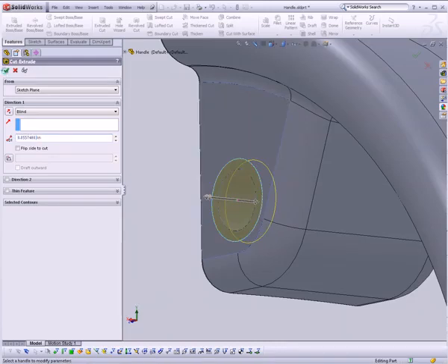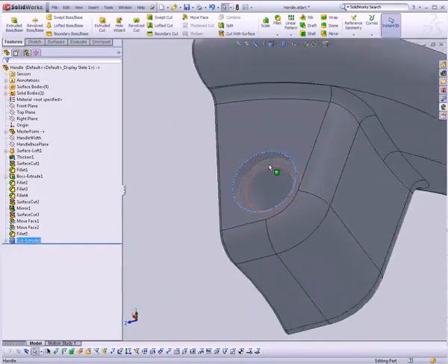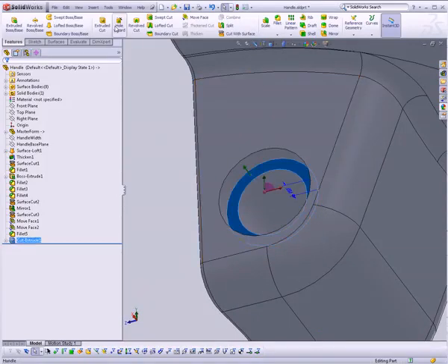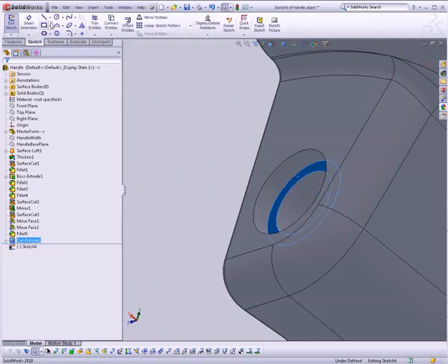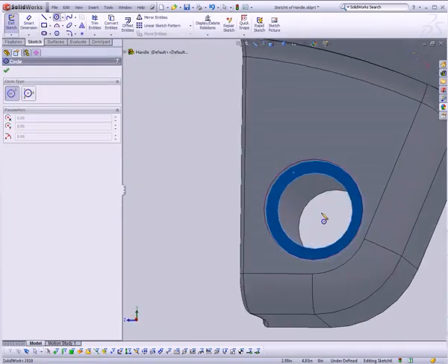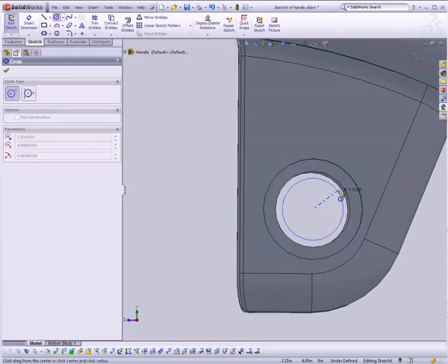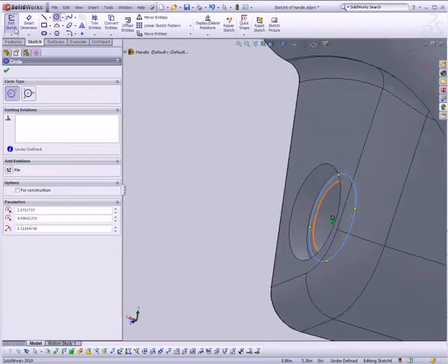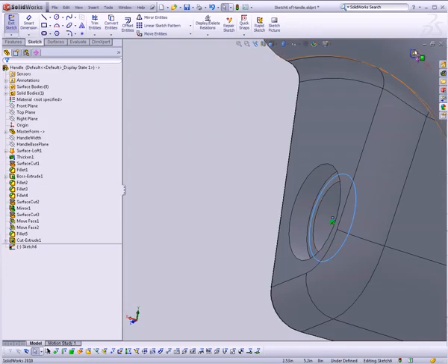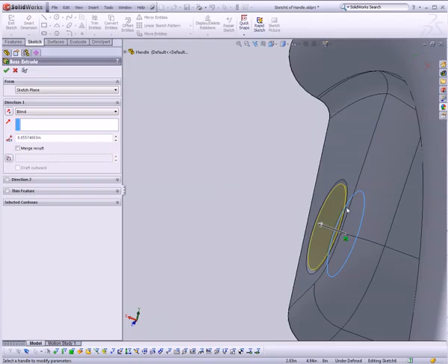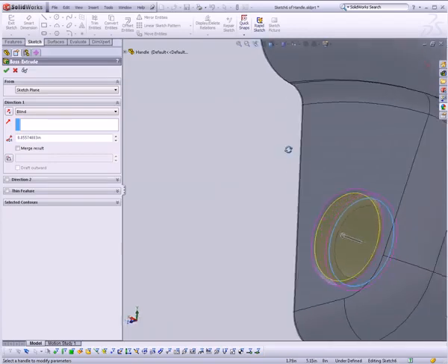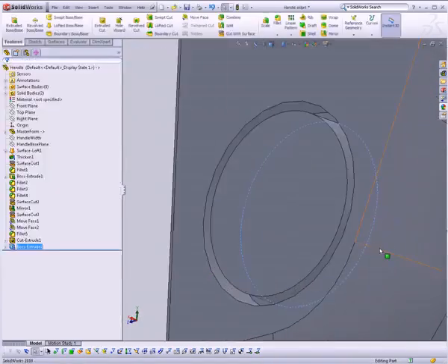And then I'm just going to add a screw just right in here, just throw in a screw head, because otherwise it's just too much time. More time than we need to spend. So we'll just do an extruded boss, throw in a circle, right about there. And when I do this extruded boss, I want to make sure that I uncheck merge result, because I don't want it to actually boolean with the rest of this. I want it to remain a separate body so we can work with it separately and give it a separate material and all that kind of stuff.